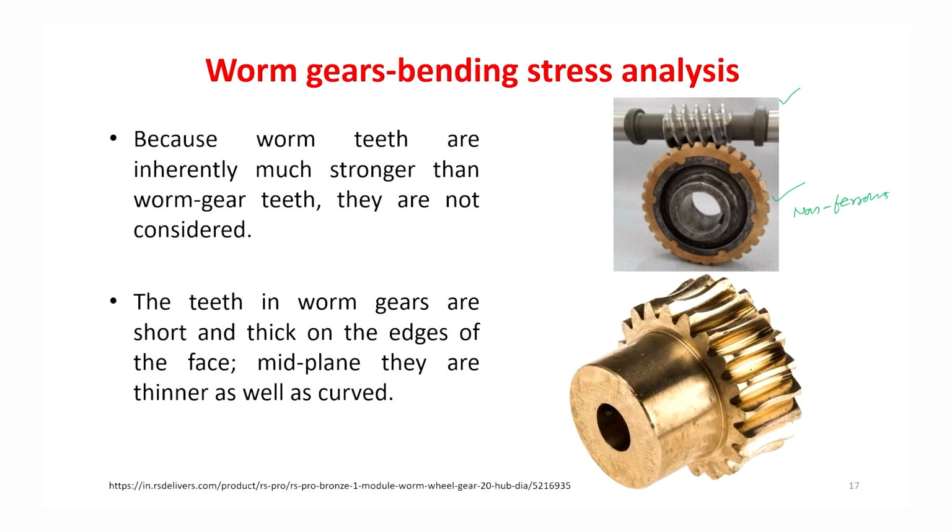You see the teeth of the worm gear, it is something like this at the edges, and when you are moving towards the middle, then it is curved and shorter, because of the enveloping nature. So, at the ends they are thicker, but in the mid plane they are thinner as well as curved. So, we have to take care of all these.